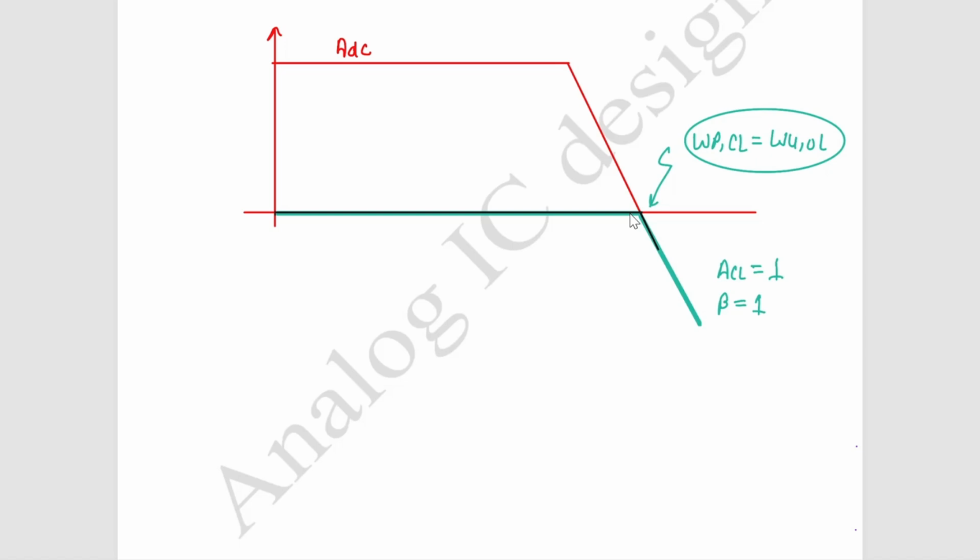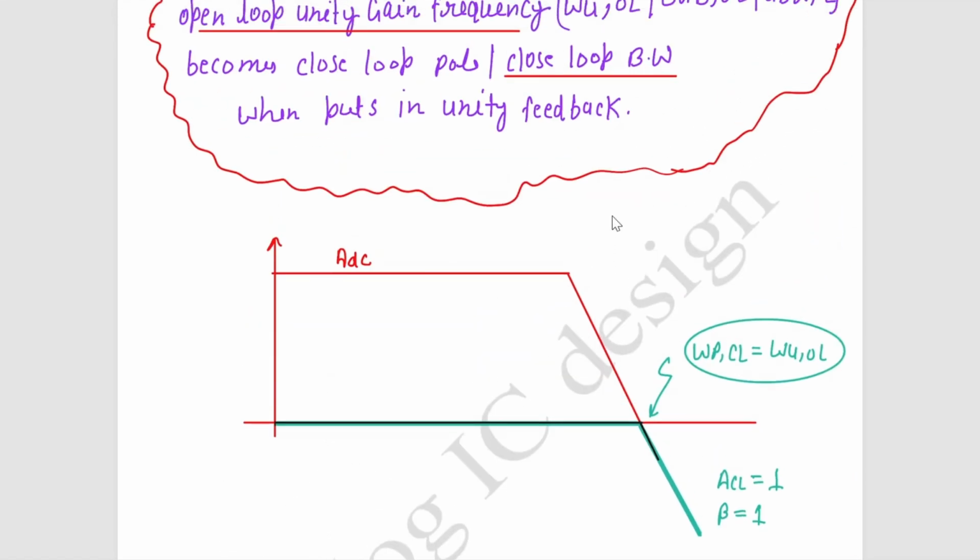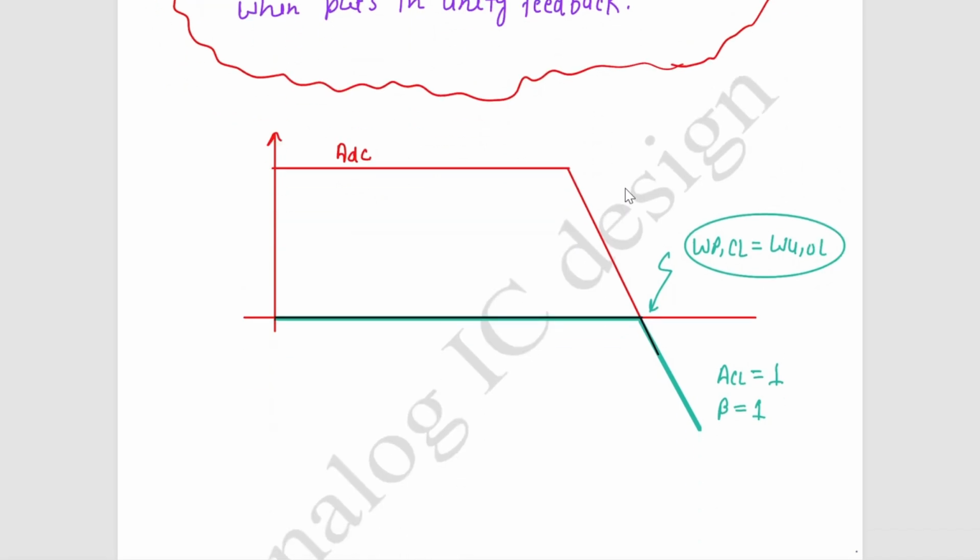So in that case, sometimes we define two gain bandwidth products. Okay, so when you see data sheets, I have seen some Texas Instruments data sheets, they define two gain bandwidth products. For one frequency range, there will be one gain bandwidth product, and for another frequency range, there will be another gain bandwidth product. So you have to see which pole location you have to use for designing the question. Are you considering your unity gain frequency as DC gain times the first pole location, or DC gain times the second pole location? Okay, so it completely depends upon your compensation. Are you able to make the system completely first order, or will you not be able to completely compensate to first order?